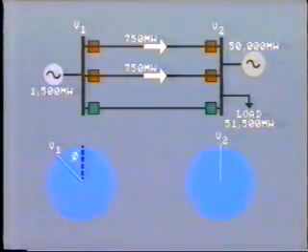As long as these areas are equal, the system will remain stable and ride through the disturbance, in this case, the loss of one transmission line. During the dynamic period, the system has quickly settled into a new steady state, with the generator advancing in angle in order to continue to transfer 1,500 megawatts along the two transmission lines.